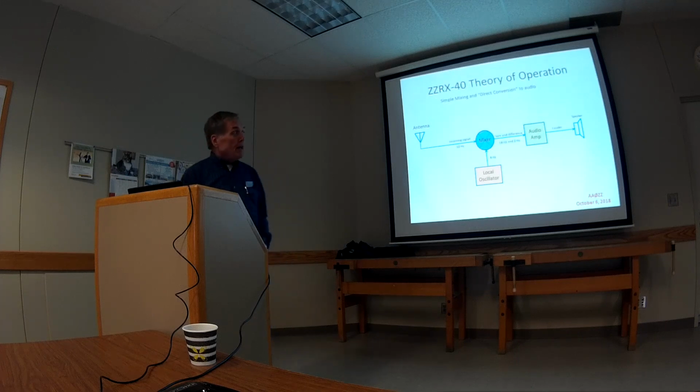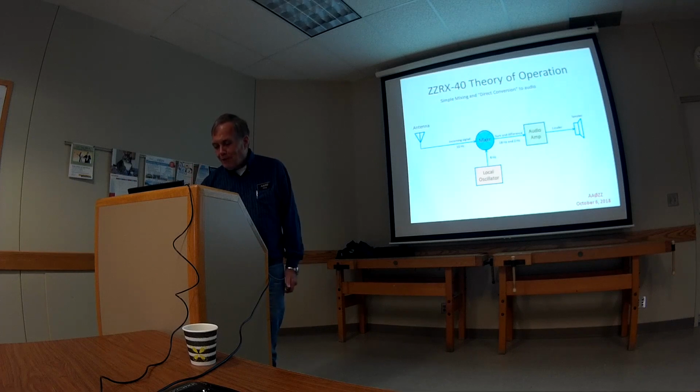So now, how does a mixer work? Well, these are artificial components, but just to show you the theory of how it works. If you had an incoming signal at 10 hertz and a local oscillator at 8 hertz, what are you going to get out of a mixer? You're going to get the sum and difference, which is 18 hertz and 2 hertz, right? And then the audio amplifier makes it louder, even though this is really low, it probably wouldn't even show up.